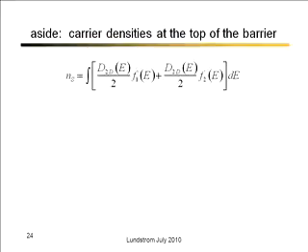Remember, early on when I told you, when we want to compute the number of electrons in the channel, we integrate half the density of states times the source Fermi function, because the plus velocity states can be occupied by the source. We integrate the other half of the density of states times the drain, because the electrons that come in from the drain have negative velocities. But the voltage is so high that F2 is almost 0.